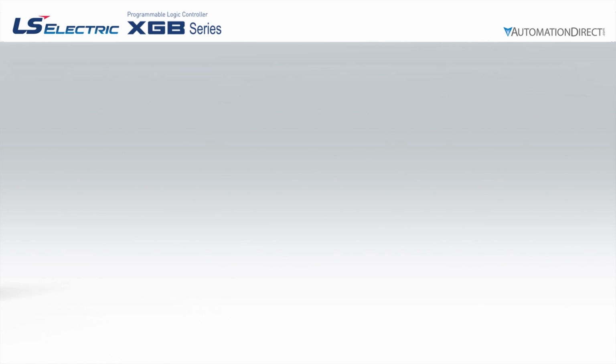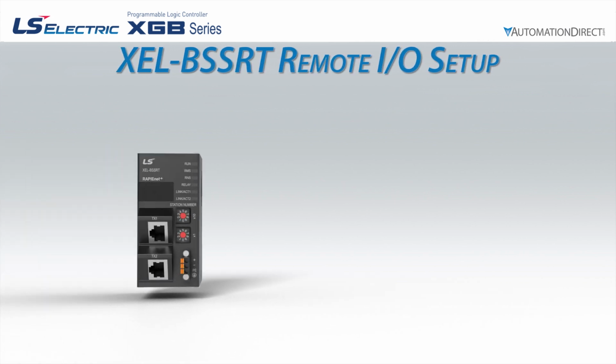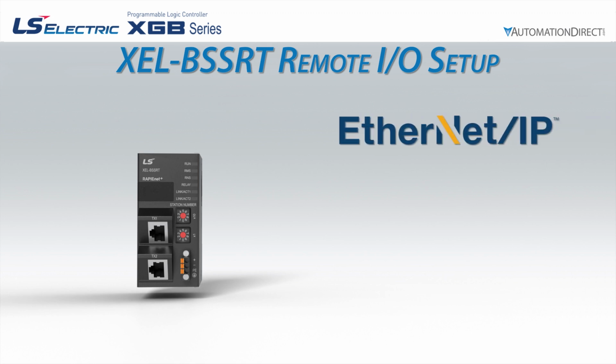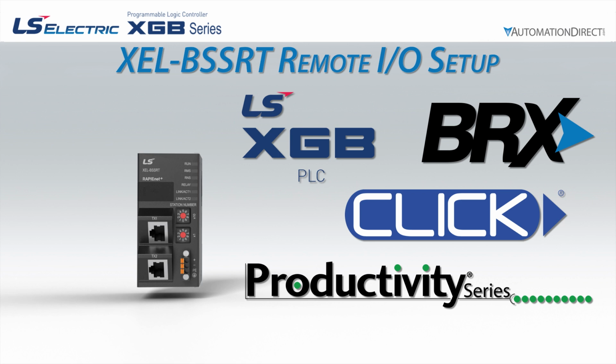One of the great features of the XGB PLC family is the ability to use remote I/O. The XEL-BSSRT remote I/O module is capable of Ethernet IP implicit and explicit connection and Modbus TCP communication with controllers or devices on its network. It is flexible and works with many different manufacturers' controllers.